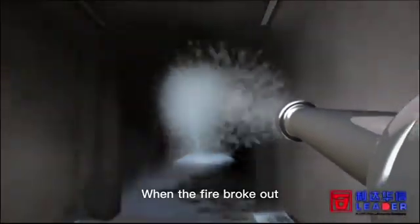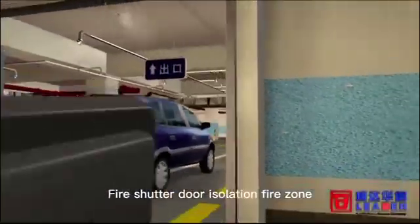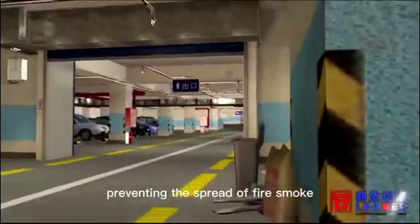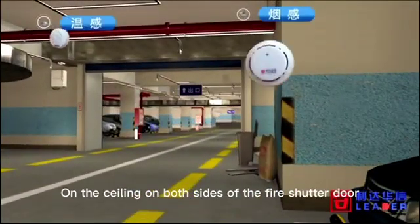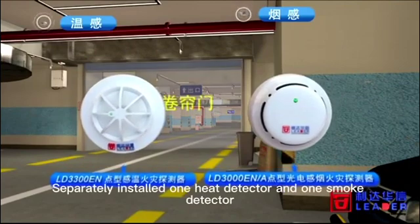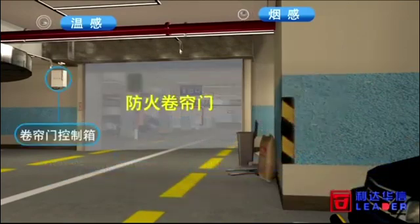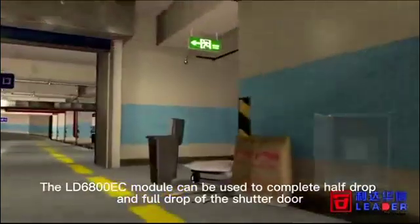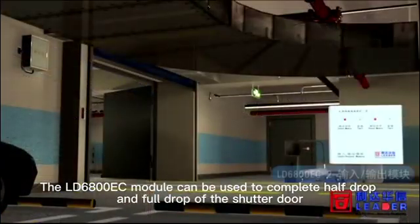When the fire breaks out, the fire shutter door isolates the fire zone, preventing the spread of fire and smoke. On the ceiling on both sides of the fire shutter door, one heat detector and one smoke detector are installed separately. The LD6800 EC module can be used to complete half drop and full drop of the shutter door.